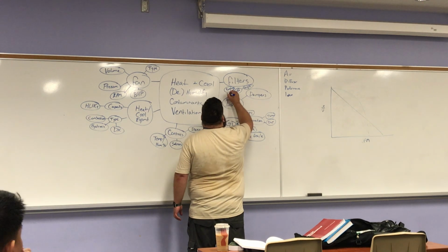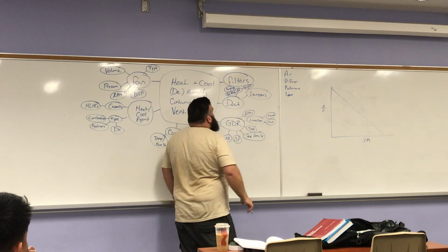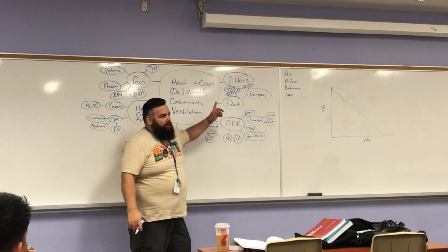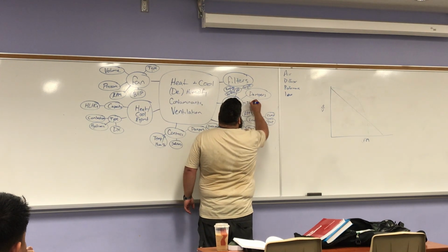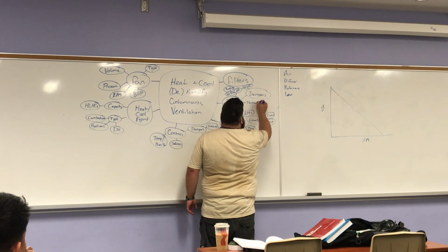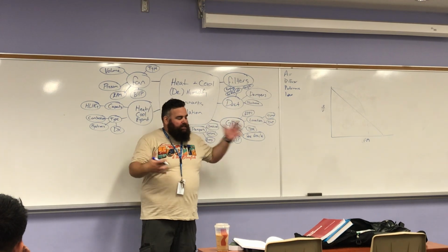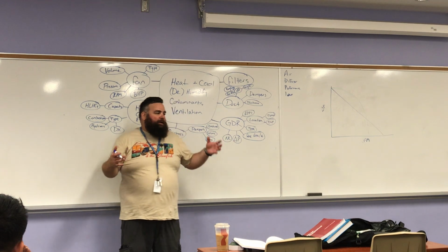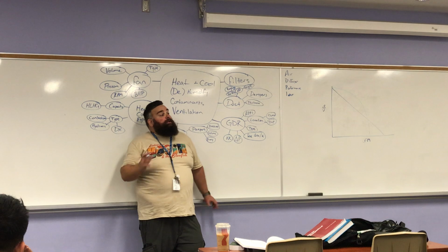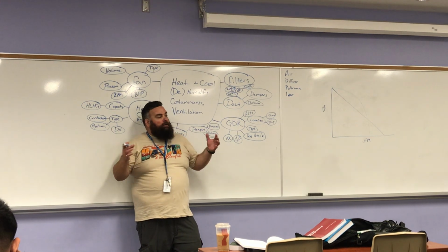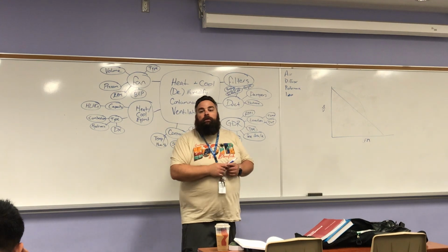Let's say free area. What about the thickness of the metal? So the thickness is immaterial. Actually, no, that's very good. It's immaterial to the pressure performance of the system. The thicker the duct is not going to impact the pressure. What it will impact is the sound and the ability to install it properly. So the bigger the duct, the thicker it must be. Shape. Excellent.